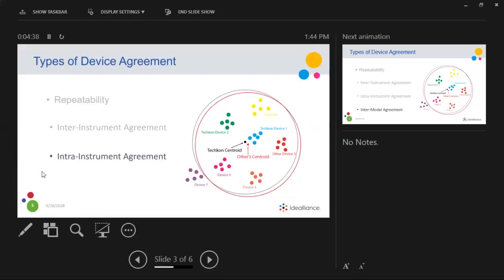Now, if you have multiple devices, you should generally see sample measurements spread inside the ring evenly without any bias. When you notice a device is outside of the device tolerance range, that device should be put aside for some extra analysis. We are going to talk about how to evaluate and troubleshoot such a device later in the presentation.